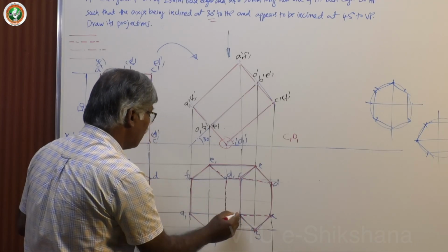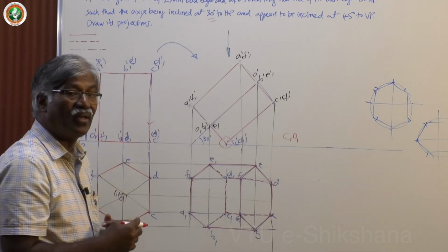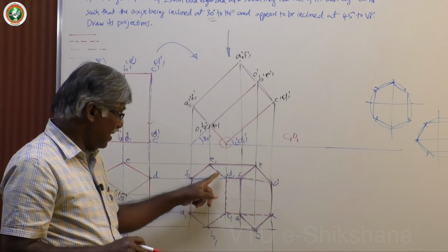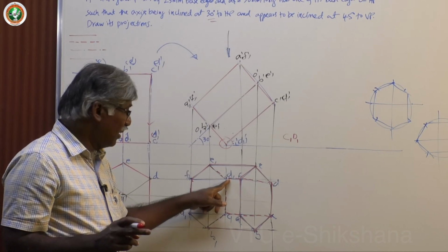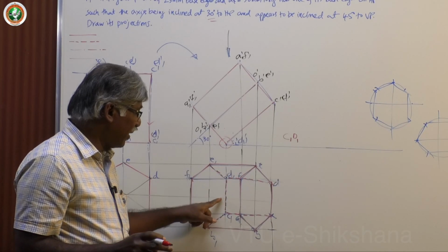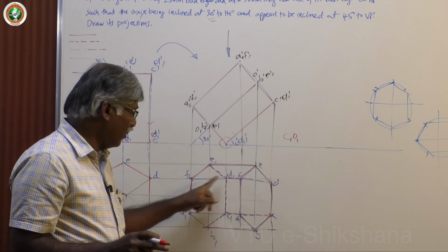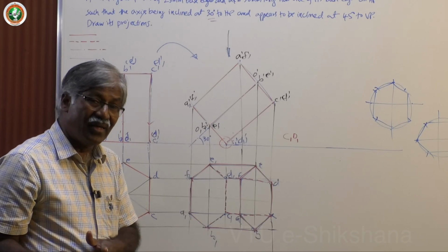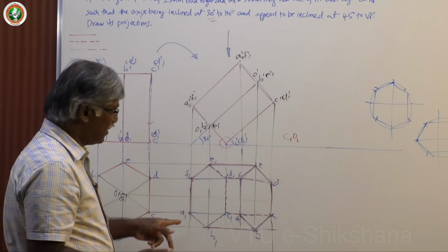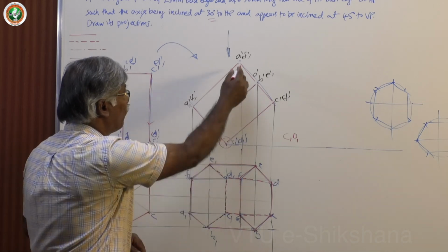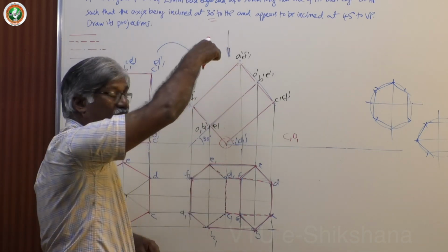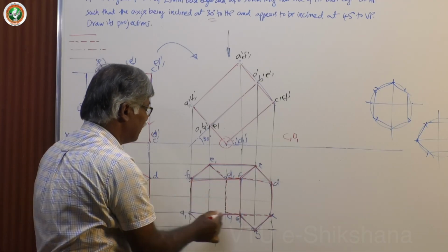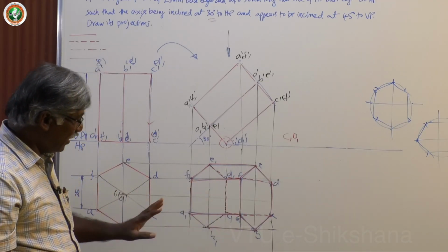Okay. So, what about AA1 and FF1? Again confusing, because he says other than boundary line, these lines are dotted, that is invisible. But what about FF1? For this reason, it is better to go for key surface concept. Otherwise, also I can say FF1 and AA1 is very close to the observer. Definitely that particular rectangle is visible. Draw. That's all. Now it has completed.